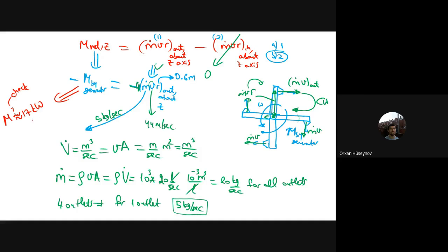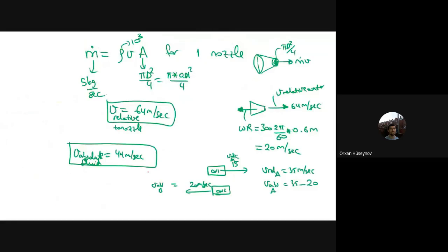You see, it is a very large number, but in reality you will have friction, therefore this will be less. Friction means efficiency. If the efficiency of this generator is, for example, 20%, you will have 1/5 of this number, which makes about 3.2 kilowatts. Anyway, it is a good number for the flow rate of the system.